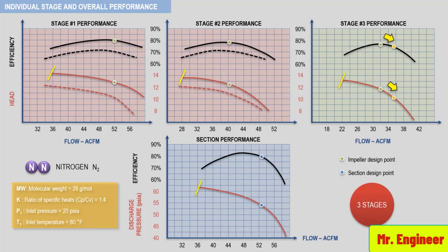So, reduced head with increasing flow and reduced efficiency. The same effect would occur if the interstage labyrinth clearance increased from erosion or vibration on the first and second stages. Any reduction of head produced in a preceding stage will increase the volume flow in a succeeding stage, and therefore reduce the overall head produced by a compressor section, as depicted here.